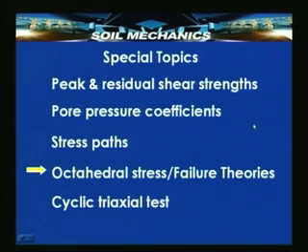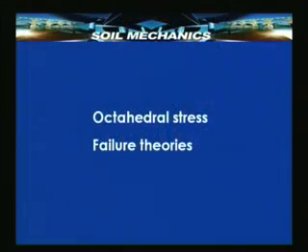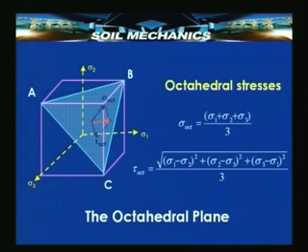Now, we pass on to an important topic from the point of view of failure of soil, since we are now talking about failure: octahedral stress failure theories. What are octahedral stresses and what are failure theories associated with that? Here is a very simple illustration of a three-dimensional stress state: sigma 1, sigma 2, sigma 3. This is a stress cube which shows what are the stresses on different planes. We are interested in one particular plane depicted here as ABC.